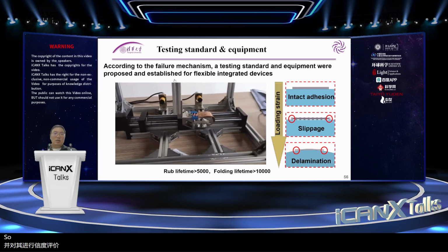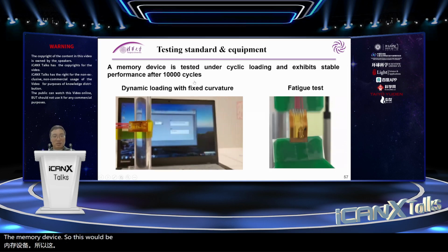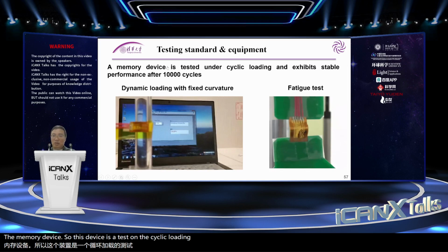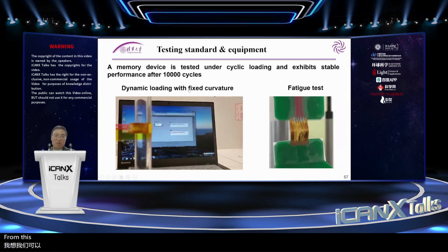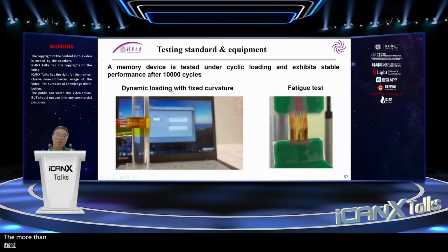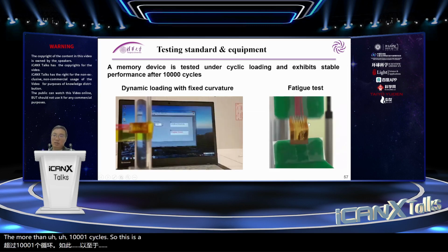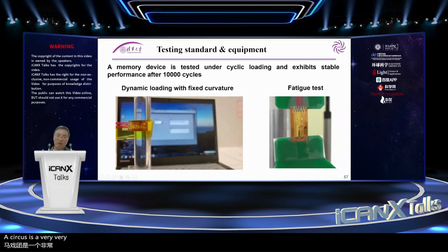So this is a flexible memory device. This device is tested under cyclic loading. It's very stable and very robust. For dynamic loading with a fixed curvature, it withstood more than 10,000 cycles. This is a fatigue test. So the flexible chips and circuits are very reliable.